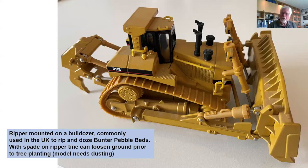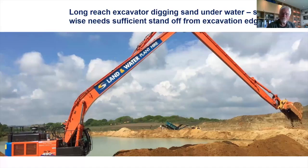This is a bulldozer. You probably need a bit bigger one to do any real work, but this is a model. I bought the first D11R that came into the country, and these are used to rip. This ripper at the back here is pulled through rock, particularly the bunter pebble beds in the Midlands, and it gets very, very hot, and it's quite noisy. But with a single pass, you loosen the rock, and then you use the front of the bulldozer to push it over the face, and it's picked up by a loading shovel and put into a field conveyor usually, or maybe dump trucks. So again, a commonly used bit of kit.